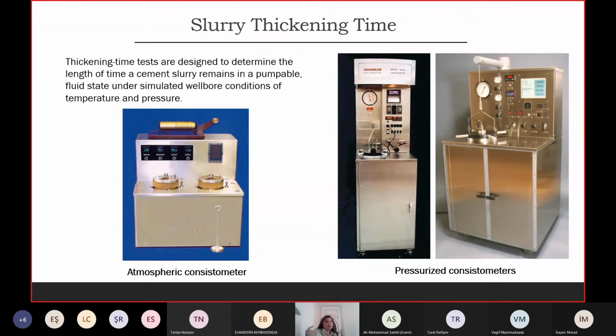So for the surface casing, by logic, we will need less time. That's why we don't need the usual thickening time from G-type cement, from Portland cement, which will be, let's say, 7 hours. It depends on temperature and pressure. So let's say 7 hours, and I need only 5 hours with the safety factor. In this case, I will add accelerator to get that 5 hours, a shorter thickening time, because I don't want to lose my rig time.